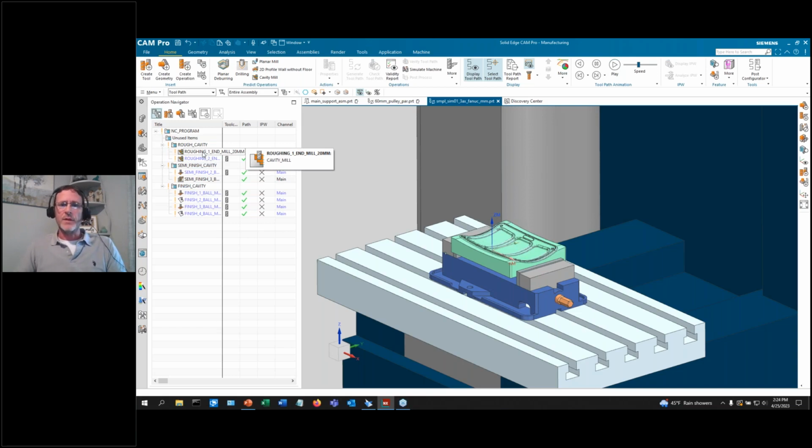All CAM systems have the ability to search through several solution sets. Meaning, if I program a tool to go a distance and then an exit move of a certain type, but it hits an over travel, all other CAM systems don't have the kinematic structure within the CAM system to know that that's even triggered. With CamPro, we do. So if we tell it to go straight line, but it hits a limit, it may alter that straight line to a loop to be able to work within those confines. So we're working within a 3D twin environment so that what we see on screen is what's actually going to be seen in real life.